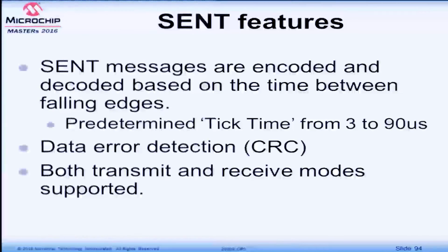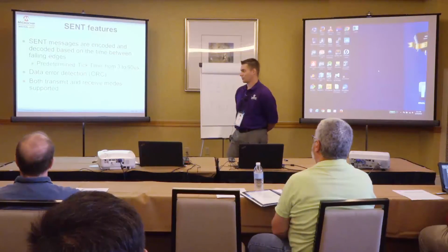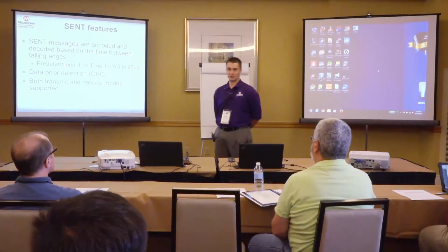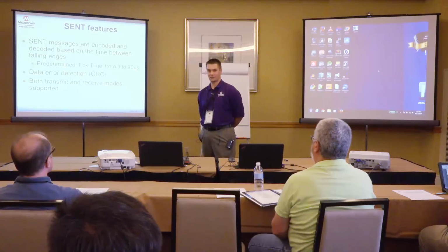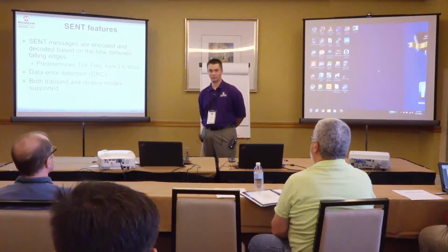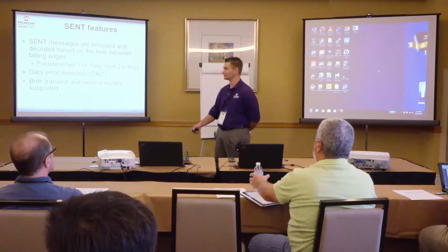It also has built-in data error detection in the form of a CRC, so the hardware calculates that. You don't need your processor to either generate or validate a CRC. And the module in our devices will support both transmit and receive modes, so you could build a sensor or some other type of engine computer or what have you with our devices.